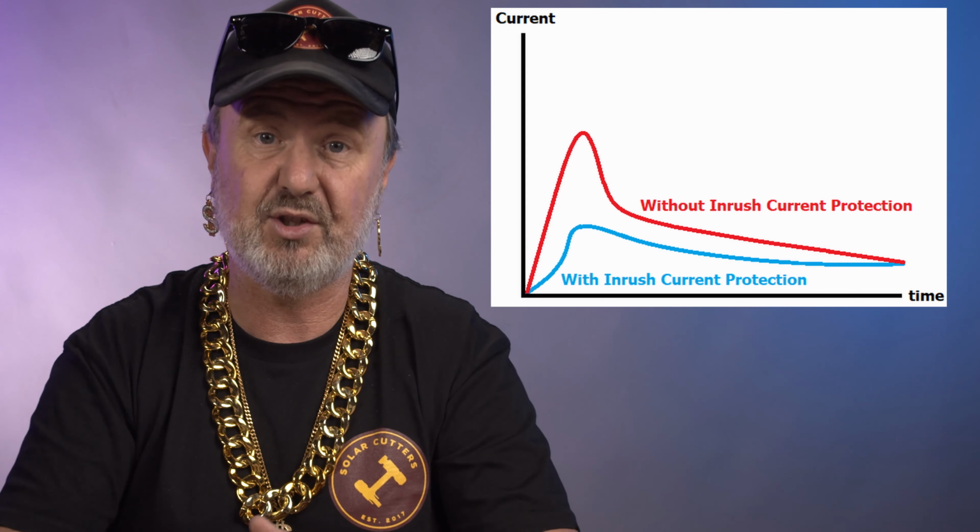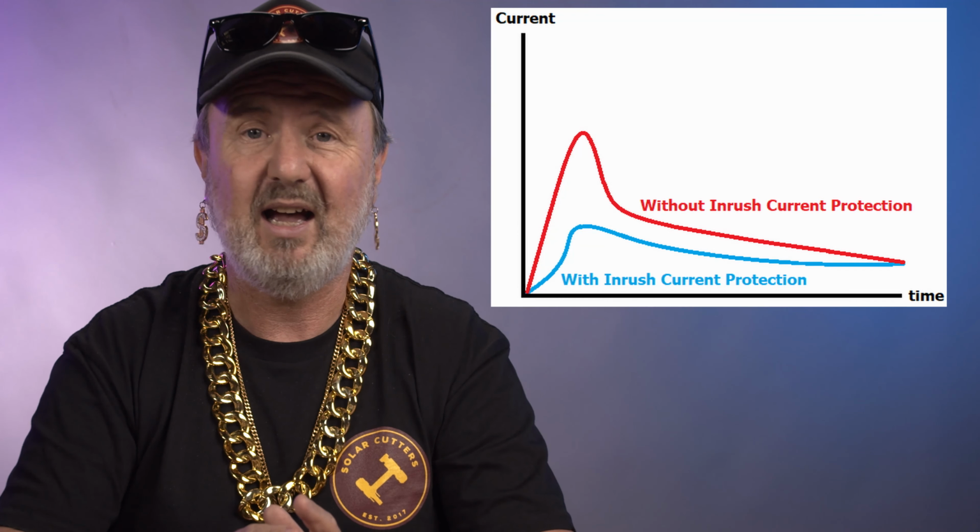So your dishwasher might turn on, it'll circulate a bit of water, little pump runs, very small load. The big pressure pump comes on, boom, it comes on with a surge, and I'll talk about surge in a second. And it's also got power factor because it's a pump. Then the water heater comes on in the dishwasher and starts heating water. So there's another 1200, 1500 watts of demand. So the two things together could be quite significant. Could be a couple of kilowatts or more.